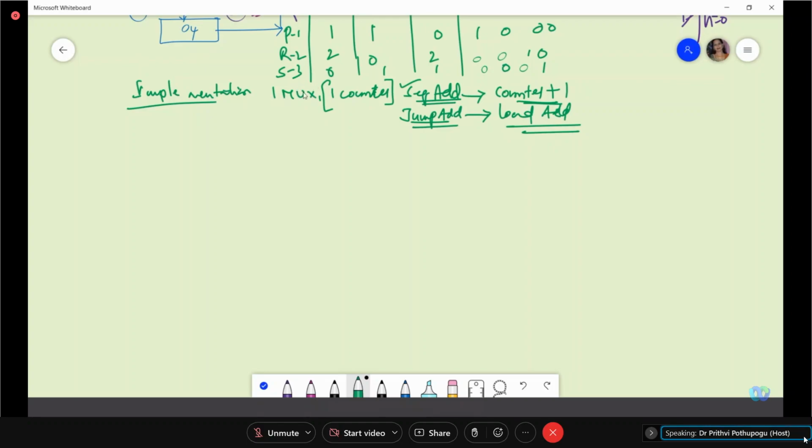And the mux will be used for finding out the qualifier value. And your ROM will be giving the value of the true false bit. Any programmable ROM can be taken, which gives you the value of the index, the true false bit, the jump address bit, and the command outputs. Maybe I'm taking 4 command outputs here.